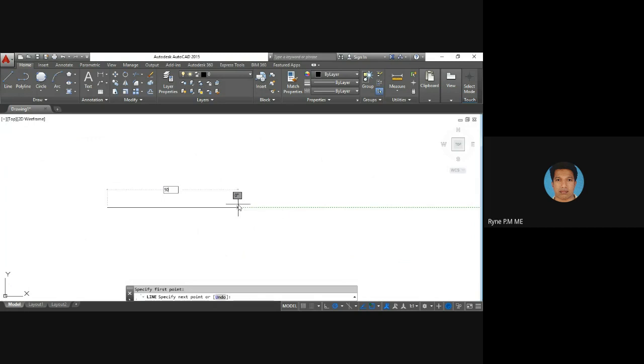So 50, you just type 50 and enter, so that you can get that 50 mm line. Now you show the other direction. So this is the next direction. You want to draw a vertical line, so set the angle as 90 degrees and draw that line, giving the dimension as 25. Type that 25 and press enter, so that we can get that vertical line also.